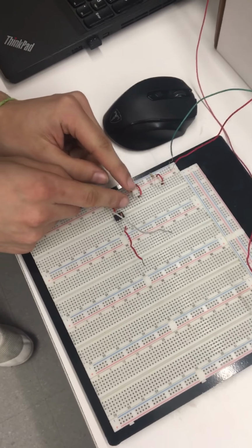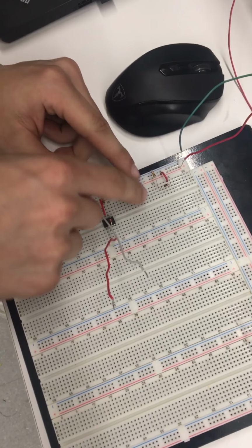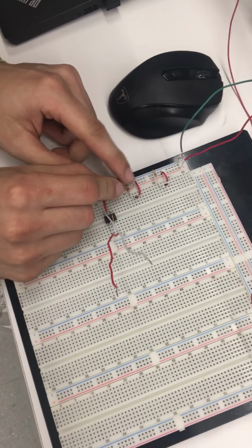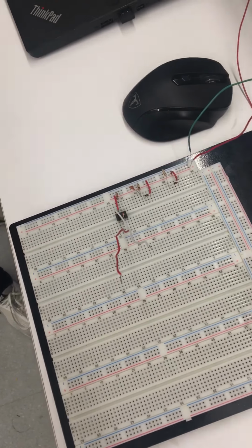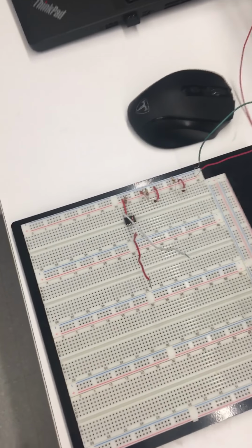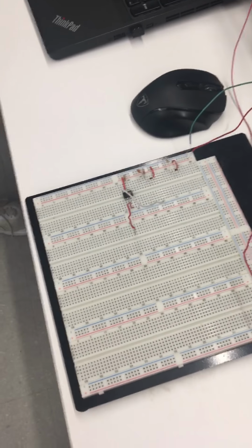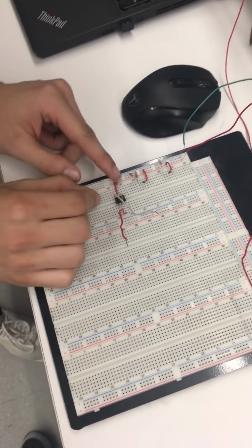The second one right here is the half wave rectifier. What it does is the voltage comes in through here, comes through the diode, and right here you have both a resistor going to ground and also a capacitor. Now what the capacitor does is it sort of sends some feedback, and basically it stops it from completely dropping off. Of course, since the diode is one way, it can't really produce a negative voltage as it would if it was a straight shot.